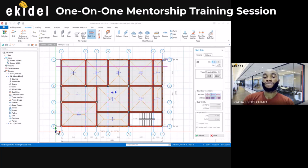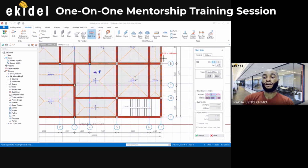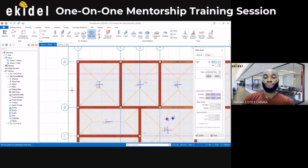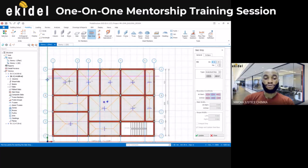And then, most importantly, these boundary conditions. Knowing that we might have a cantilever at the boundary, we can have a cantilever slab or just a slab, and then we'll have just beam as the boundary. So if I want to cut or detail a slab through this panel in the X direction here, I have a beam to beam boundary.